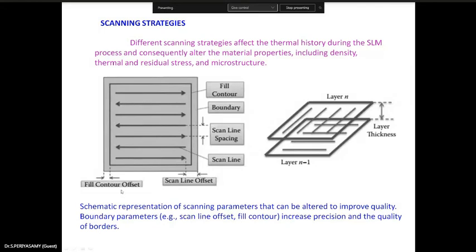So here you have a peak. Another value will be down. In these cases, the peak is here, the valley is here. So the roughness will be increased. If it is melted and lineated, you can have a straight line. So generally, both material properties and processing variables can influence the wettability and consequently balling. So you have to go for the process parameters and see how to control this.